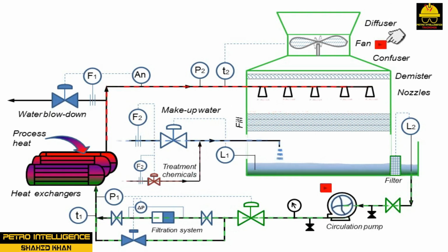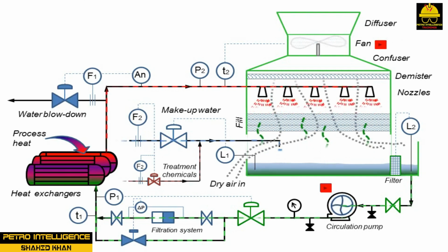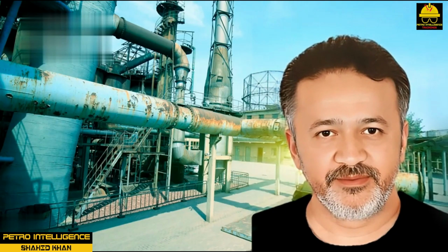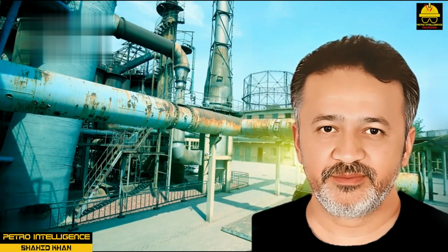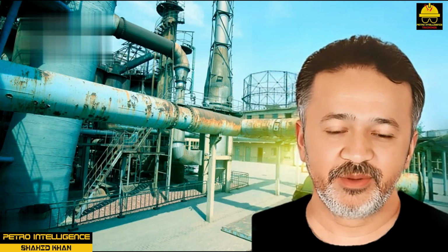Side stream filters may be used to remove airborne solids such as dust and sand and contaminants introduced via the cooling tower makeup water such as silt, organic matter, and waterborne organisms. Each filter is sized to handle the full flow while one filter is backwashing or out of service. The side stream filters operate automatically under gravity flow and are of the self-contained backwash type.